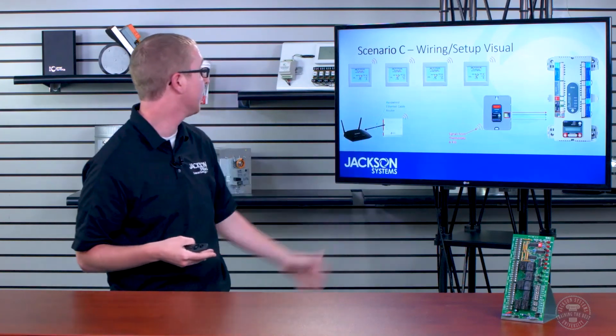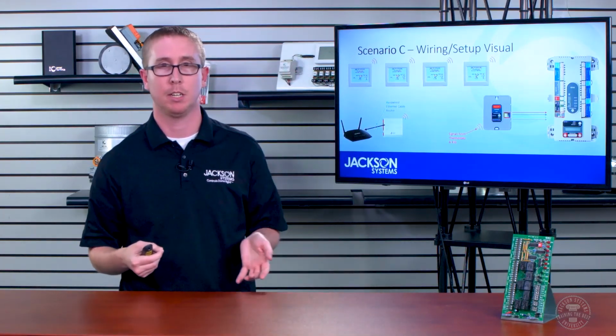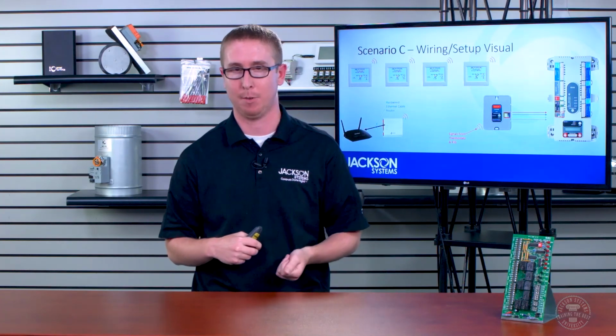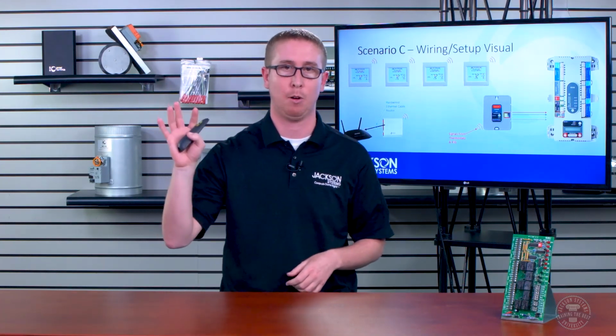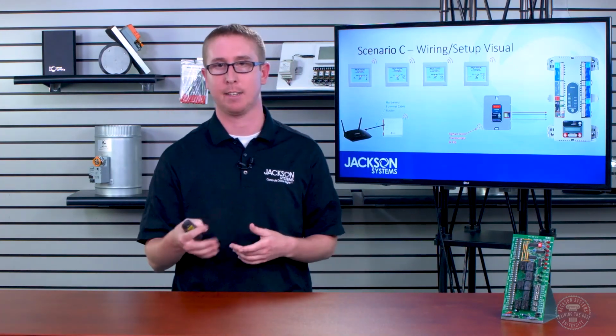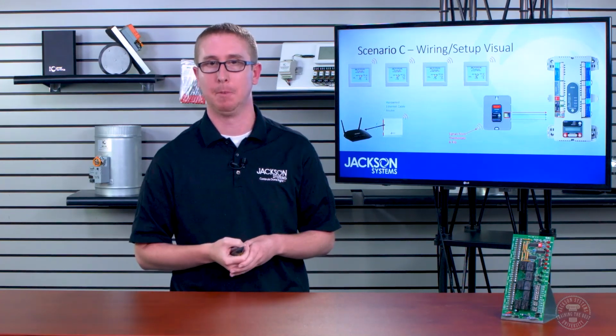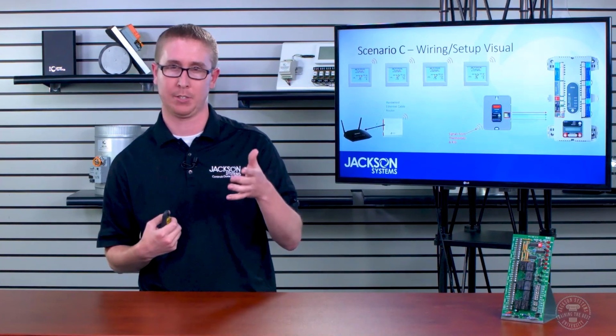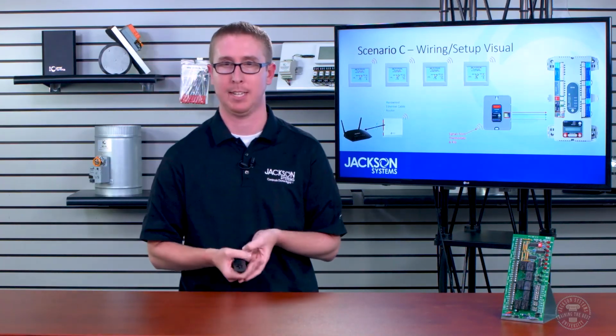This gateway just has an Ethernet cable that plugs right into your router. So it's getting that internet communication hardwired through that Ethernet cable. It's taking that information from the router and projecting it out on a RedLink signal back to that wireless zoning adapter. Again, there are no wires going from the wireless zoning adapter to the gateway or the thermostats in this scenario.